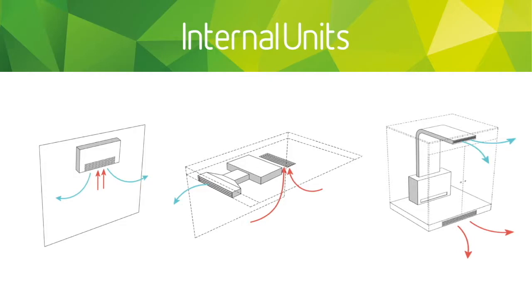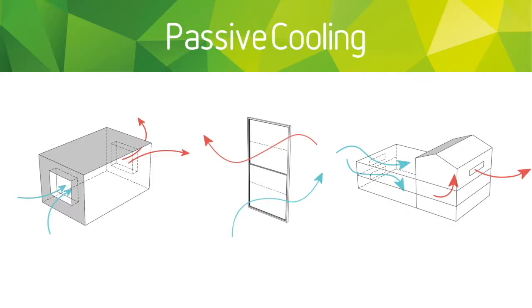With regards to mechanical cooling, it is very energy intensive. It can use a lot of energy in a very small amount of time. This is why it's often not advised. One thing to note, some manufacturers of MVHR units suggest that you put a cooling coil in your supplied ductwork. I would not really recommend that because, for various reasons, it's debatable if it really provides the cooling requirement to the space. So what is passive cooling?